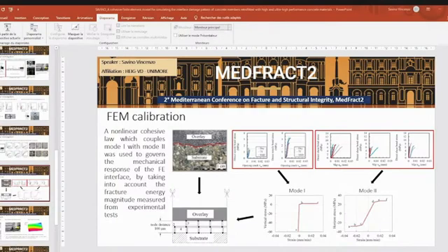Thank you. We can conclude that a simple and effective model has been developed to simulate the stress propagation along the interface of existing concrete structures rehabilitated with a layer of high and ultra high performance concrete. A family of bond testing devices was designed by the authors to carefully calibrate the mechanical response of the interface, both in mode 1 and mode 2. The model was validated by a mechanical bond test which was independent from the tests carried out to calibrate the model. Experimental investigation also pointed out that both the moisture level of the substrate surface and the fresh properties of the overlay matter, and that ultra high performance concrete is more sensitive to the moisture level than high performance concrete due to its low water-cement ratio.